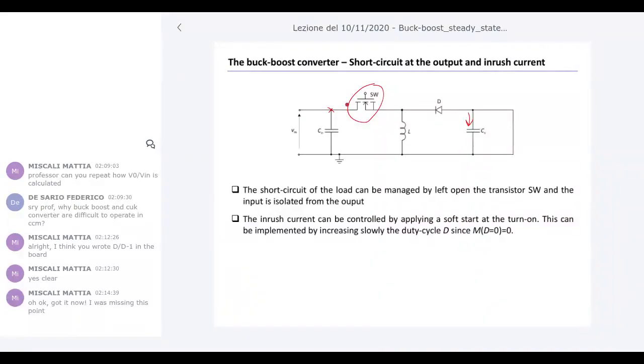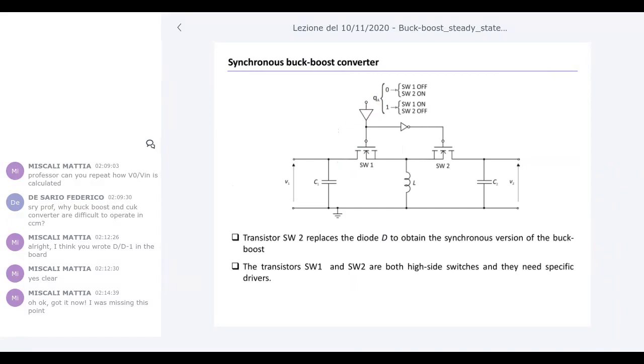That means that when the MOSFET, for example, is off, the voltage VDS can be very large, exceeding the breakdown voltage of the MOSFET. So this is something that can be controlled, trying to reduce this overvoltage at the input by filtering, etc.